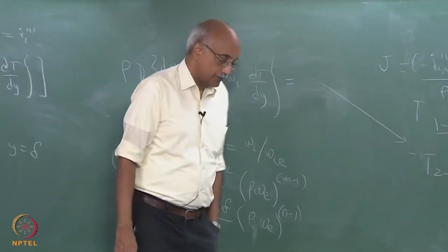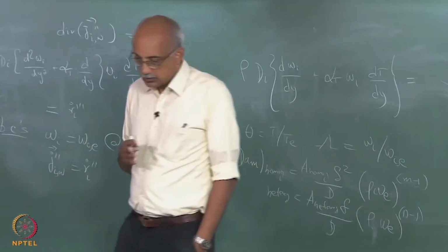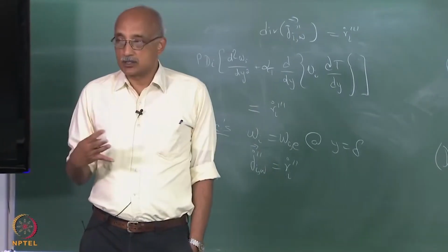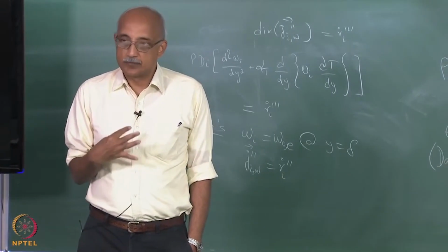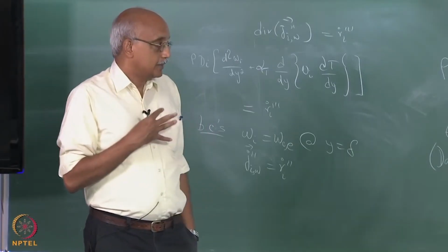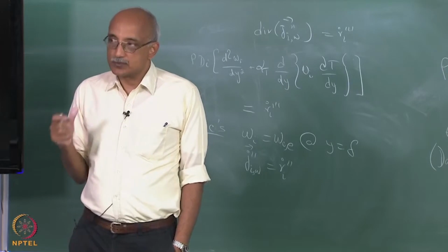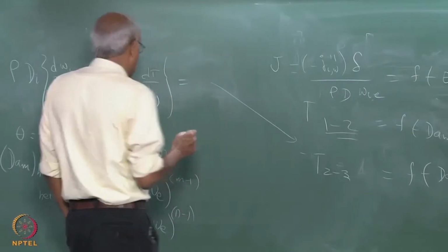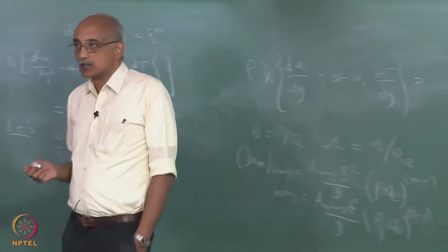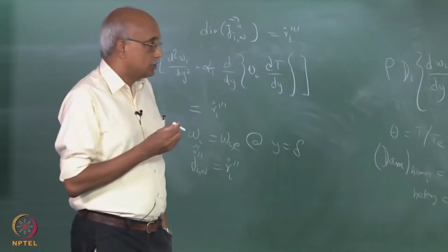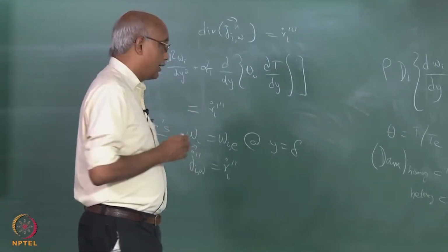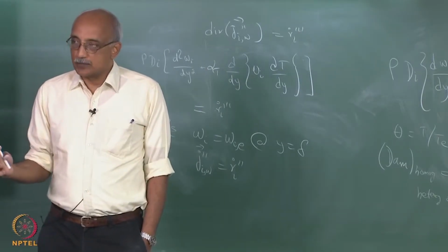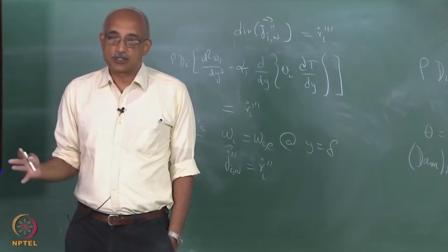Now, it turns out that if you want to drive the process to conditions where homogeneous nucleation or aerosol formation becomes possible, then the ratio of the Damköhler numbers does become important. In fact, the temperature or the conditions that favor the formation of nuclei in the gas phase have to do with how rapidly are the homogeneous reactions proceeding versus how rapidly are the surface reactions proceeding.